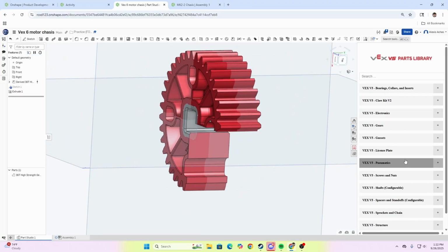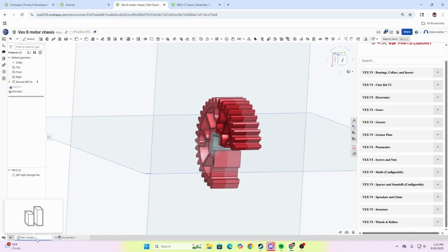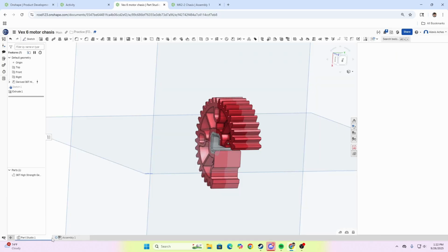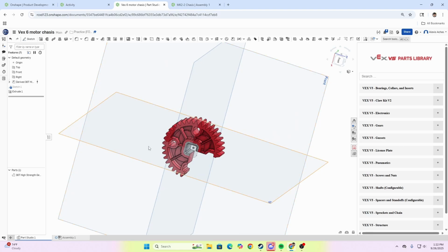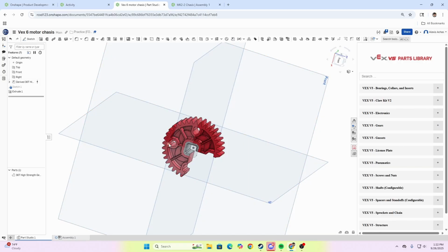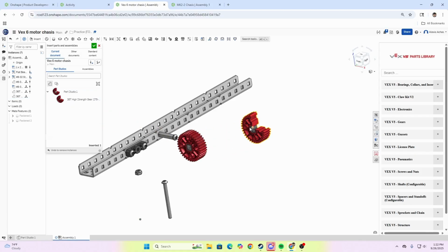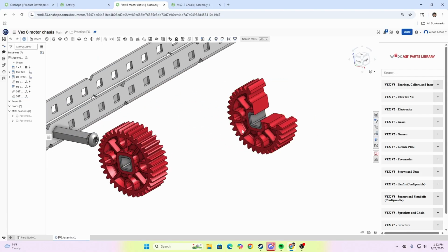So if you want to modify anything here, insert it in a Part Studio, not in assembly, right? So now you want to include this part into your assembly, and it's as simple as going to insert. You want this part specifically in your assembly, so you press insert, and it should automatically appear here as a Part Studio, say Part Studio 1. Whatever you name it, it's going to appear here. So I'm just going to click on it, and ta-da, there we go. There's our modified screw right there.